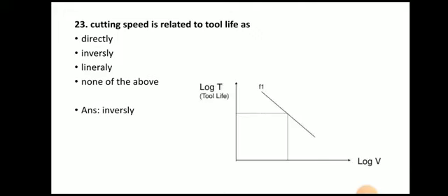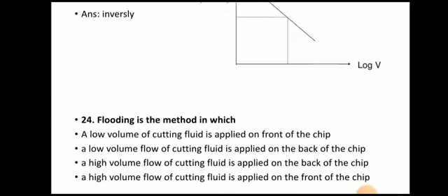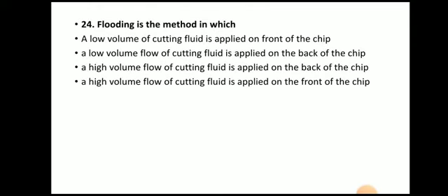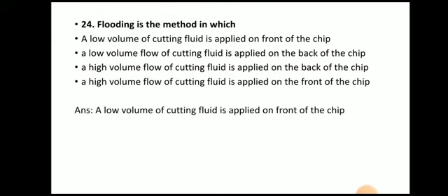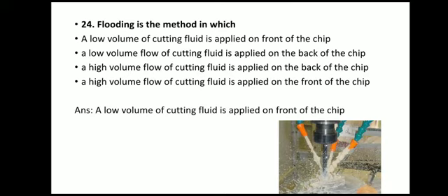Next question. Cutting speed is related to the tool life as. The answer is inversely proportional. So the cutting speed is inversely proportional to the tool life. As you increase the cutting speed, the tool life reduces. Next question. Flooding is the method in which. The answer is flooding is the method in which a low volume of cutting fluid is applied on the front of the chip. Okay, so here you can see this is the flooding.